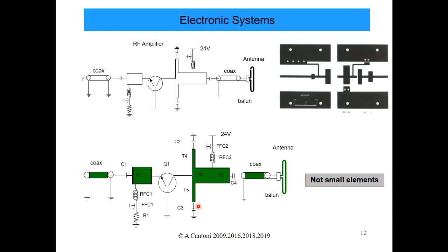So for instance, this cable here is probably a twisted pair with a shield around it, and that's the transmission line. There's probably a number of pairs, and between each pair there's a signal being transmitted. At one end a high-speed signal is launched into that line, and it propagates with delay down that line. The delay through that line is probably a lot larger than the rise and fall times and the periods of the signal going down. So you can't consider it as a short circuit anymore. You have to have some special model for it.